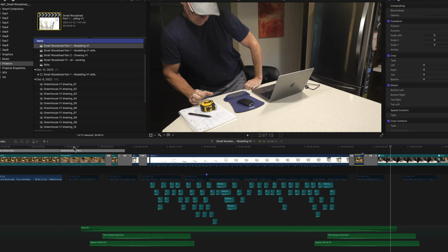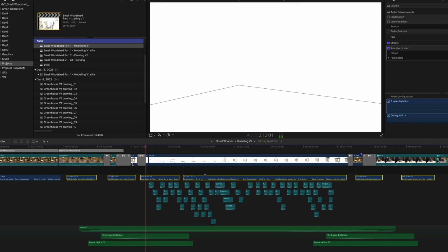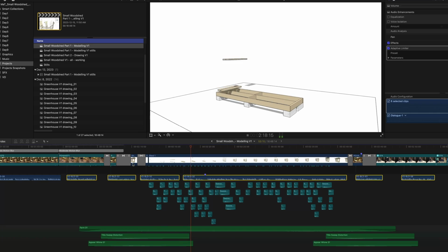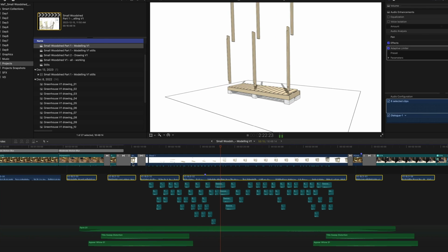Now I'll turn my voiceover back on and play it through with a description. The shed sits on 6 concrete blocks, or can be secured to poured footings with post saddles. Over the blocks are floor joists, topped with deck boards. There's 2 outside walls and a middle dividing wall creating 2 firewood storage bays.